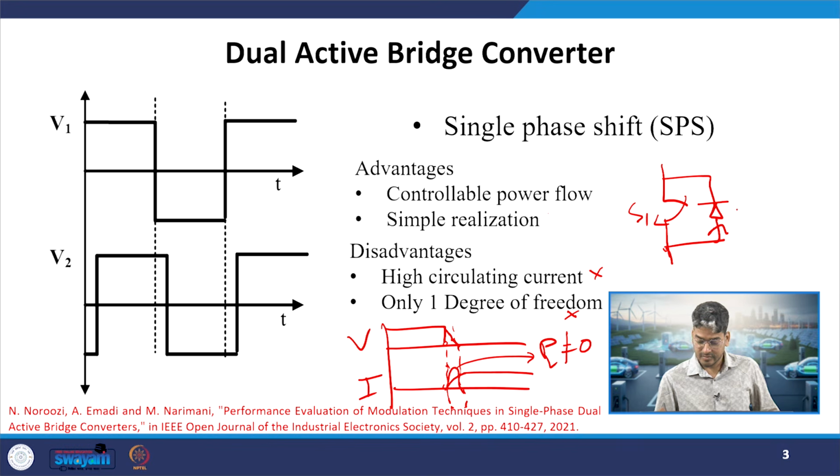So, the on state drop of this diode will be applied across the switch, which will be around 0.5 to 0.7 volts, which is nothing compared to the supply voltage, which will be around 400 or 800 as per the application. So, here if the diode comes into conduction path, the S1 will see near 0 voltage, so it will go into soft switching mode.